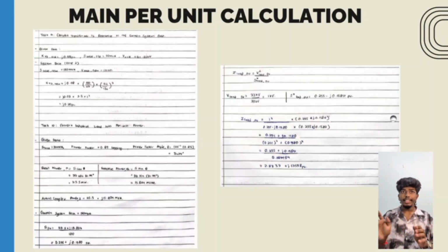Moving left to right along this single series loop, we start with our ideal internal generator voltage source, which is EG1 operating at 1 pu, followed by our calculated reactances: the generator at j0.40 pu, transformer 1 at j0.1667 pu, the transmission line at j0.2296 pu, and transformer 2 at j0.20 pu.